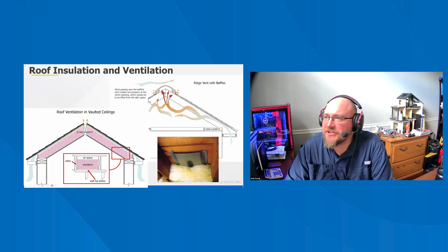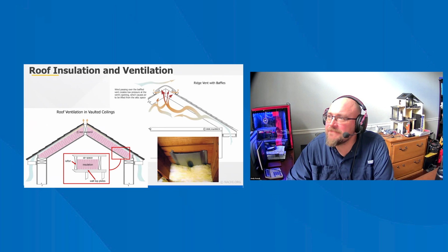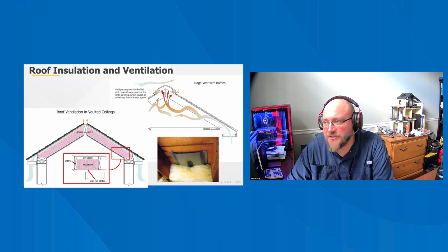Roof insulation and ventilation. Roof system ventilation and insulation are important for a number of reasons, including condensation control, temperature or heat control, energy efficiency, and the prevention of chronic ice dam formation. Ventilation of attic areas is intended to prevent the accumulation of moisture vapor in the attic roof space and to dry low levels of condensation that may form on the underside of a roof deck. Ventilation is also intended to reduce the temperature of the roof deck during hot periods to improve shingle durability. Reducing attic temperature through ventilation and insulation also improves energy efficiency during hot periods.